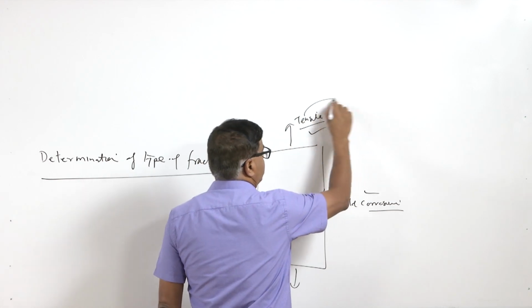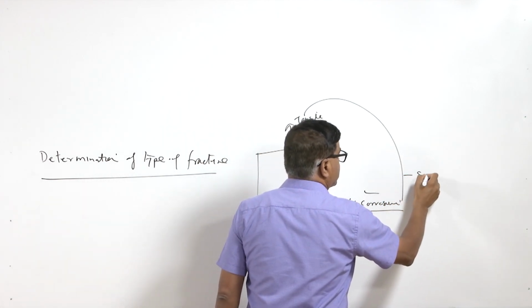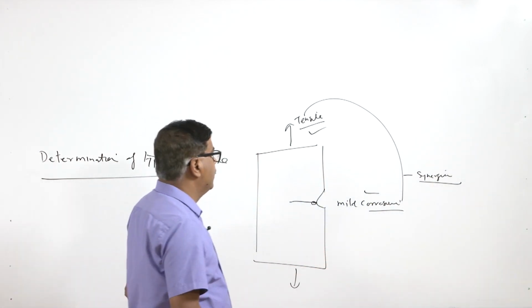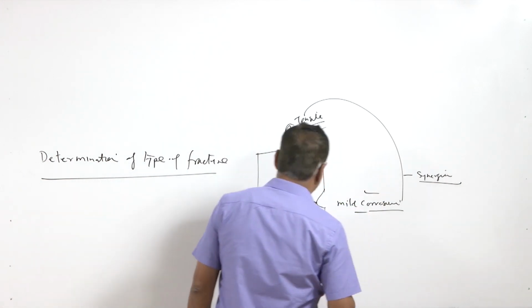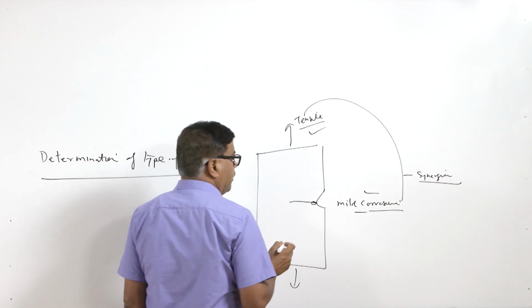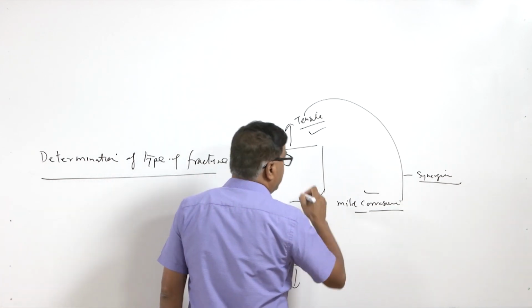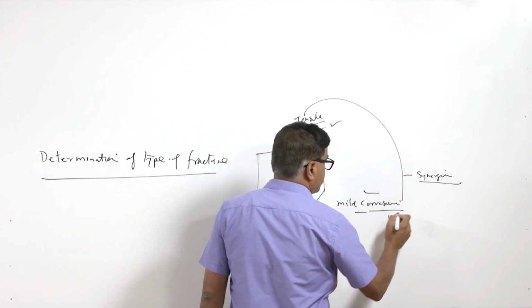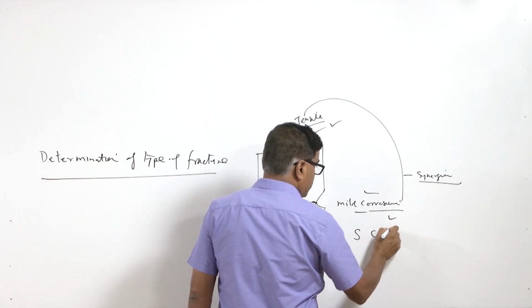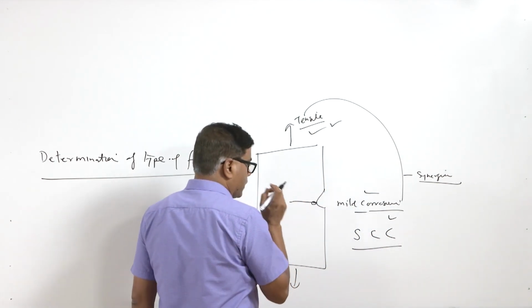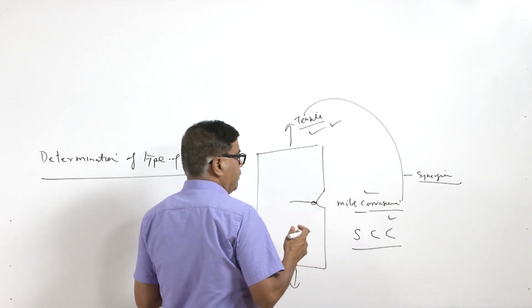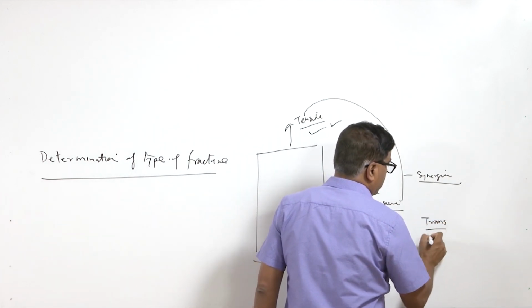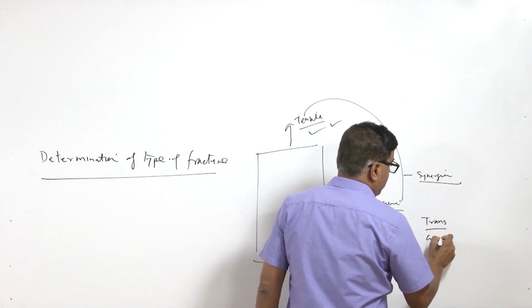Typically, when we see the presence of both, the two work in a very synergistic manner and reduce the life of the component drastically because of their combined effect. But the point is how the fracture is facilitated under such conditions. The failure of the component in the presence of tensile stresses and corrosive media is termed stress corrosion cracking. In which way the crack propagation takes place is what is to be seen. It has been observed that it can be transgranular or intergranular also.